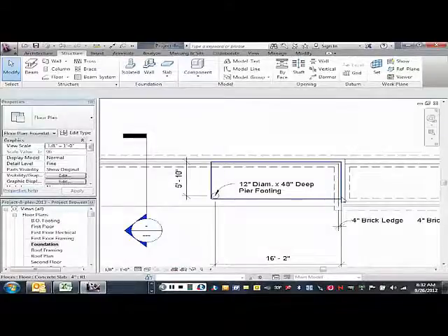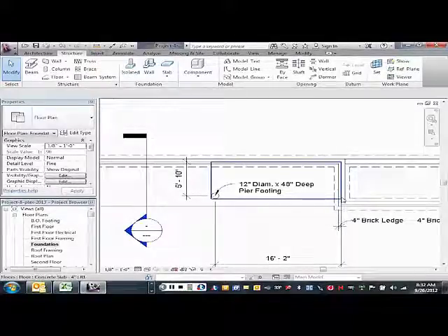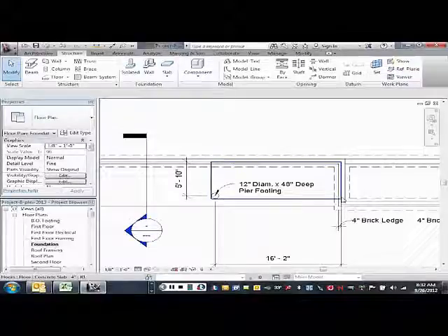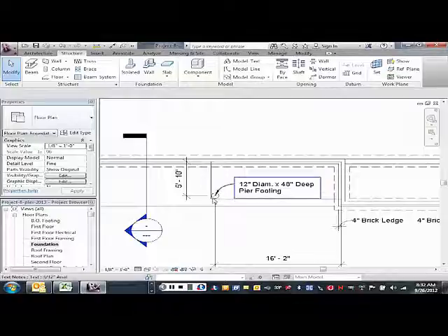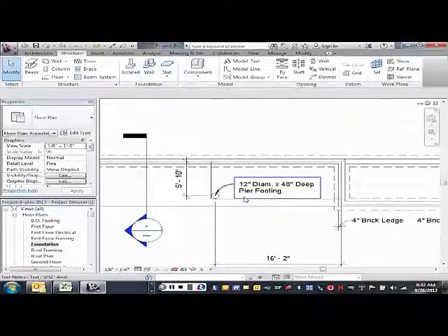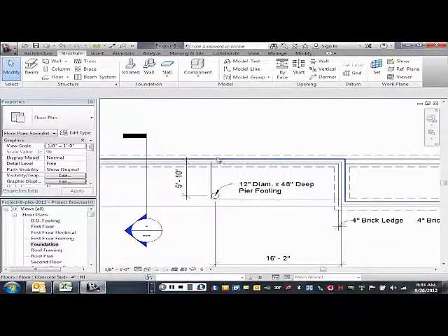The beam that's going to run across the front of this patio on the second floor is going to tie into the wall of the vestibule, right? So it'll be sitting on studs within the wall, coming out and sitting on the post on the other corner. So therefore I only need a post out here because the beam ties into the wall on the back, just like the joists tie into the wall where the patio door is, right?